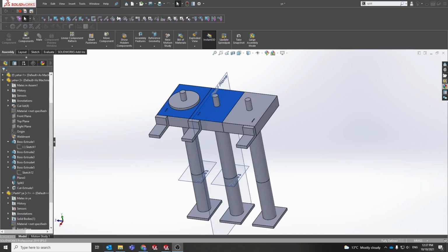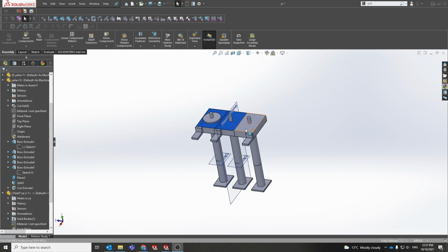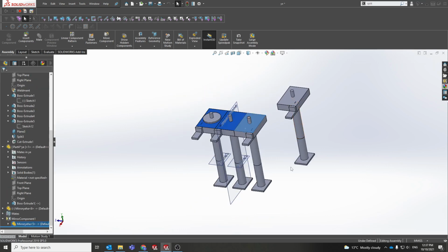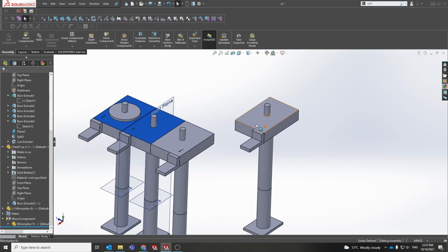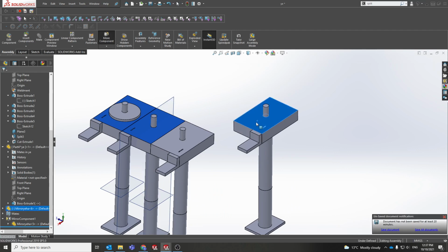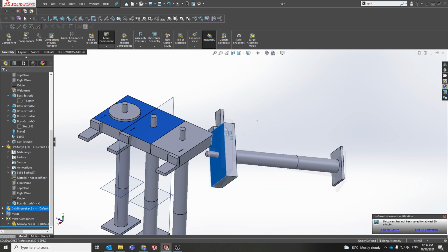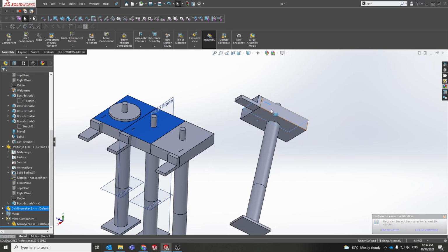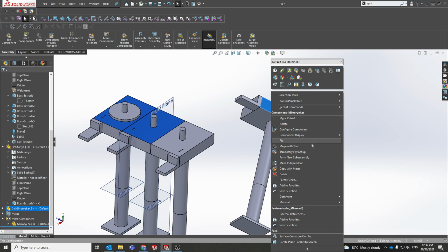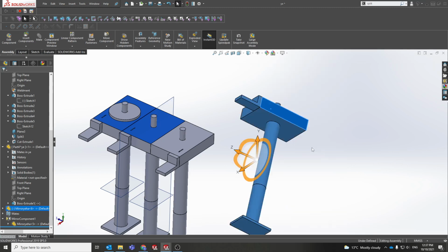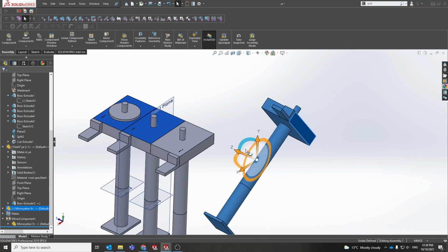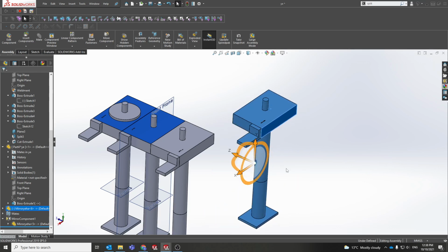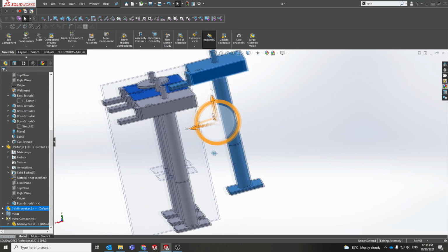Just recording this in post, I did miss a simple tip in the assembly. So obviously if we've got an extra part here, if I wanted to rotate this to try and see something would fit, I can do that by, if I use the right mouse click to click on it and drag it, it actually rotates it like that. You can also move with triad as well as another one. So this is the more traditional, up, down, rotate way to do things. But that's something that can be used to move things around the assembly.